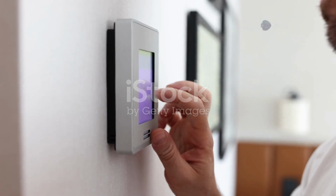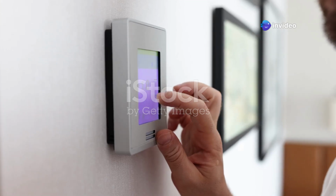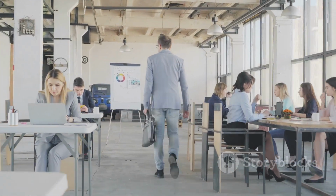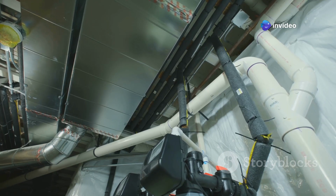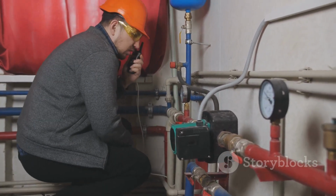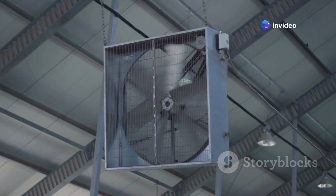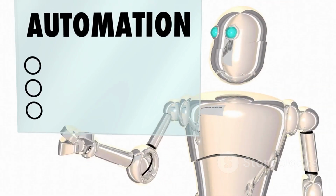Throughout the busy workday, temperature sensors in different zones of the building continuously monitor the thermal conditions. If a particular area, perhaps a sunny meeting room, starts to get too warm, the local temperature sensor reports this to the controller. The controller processes this information. It then commands the cooling system to counteract the temperature rise in that specific zone. This might involve instructing an actuator to open a valve, allowing more chilled water to flow to that area's cooling coil, or it might increase the speed of a variable air volume (VAV) box fan. All this happens automatically without manual intervention.